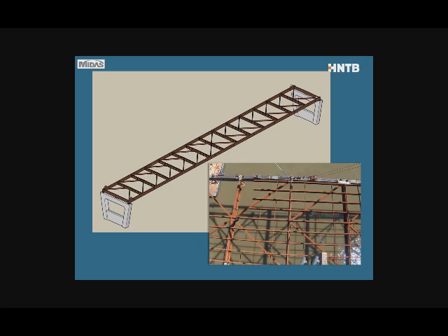Okay, next stage, I've added the bracing. This is the lower lateral bracing, which serves as deck bracing during construction stages. And in our case, the bridge is very wide, 107 feet center to center of floor beams. And so to prevent lateral torsional buckling of the floor beams, the bracing system actually engages the top flanges of the floor beam and holds them against the lateral torsional buckling.